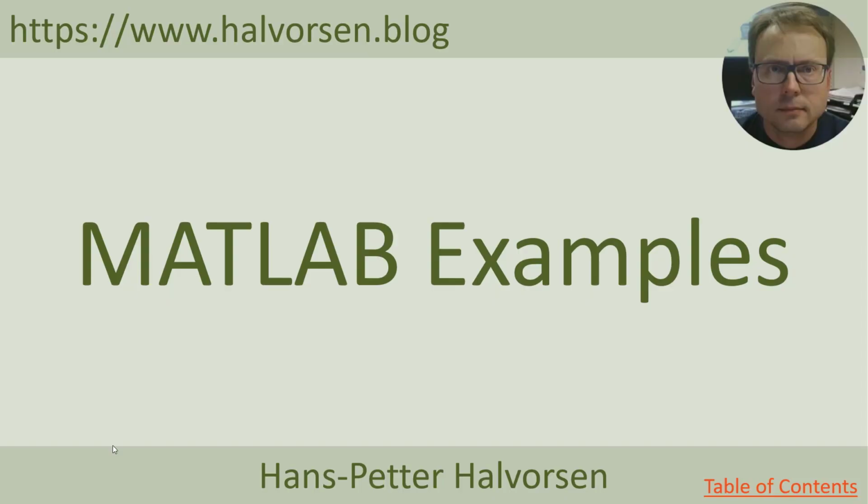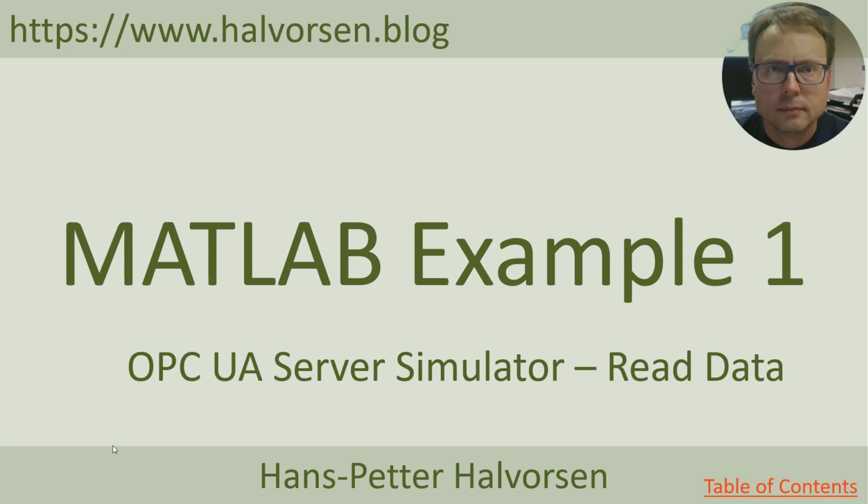Then let's start creating some basic examples in Matlab. So example number 1, we will use this OPC UA Server Simulator. And then we will create a basic script in Matlab that is reading values from this OPC UA server.